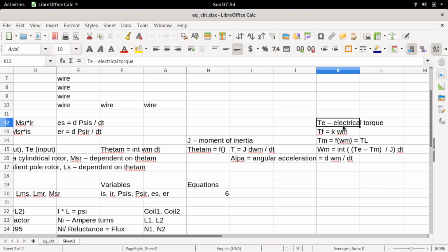And we had said that if these rotor bars carry a current, then because these rotor bars will be in the magnetic field of the stator, they will experience a mechanical force, and this mechanical force is described in this direction. And similarly, for the lower slot, the mechanical force is described in this direction. So if there is a mechanical force in this manner, it is quite obvious that it will produce a torque, and this torque will cause the rotor to rotate in the counterclockwise direction.